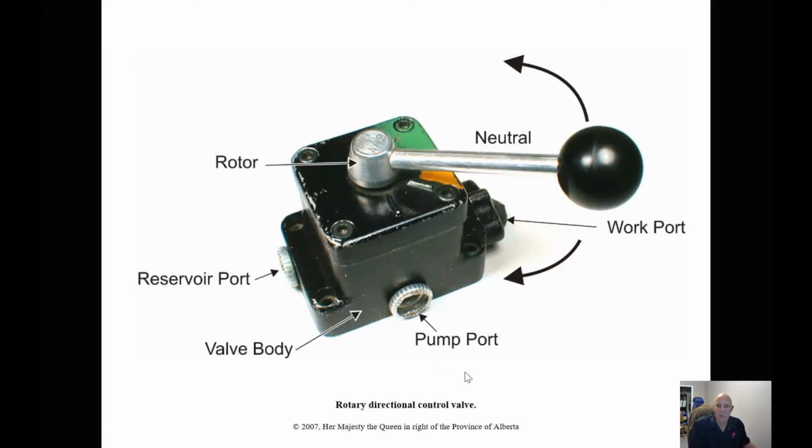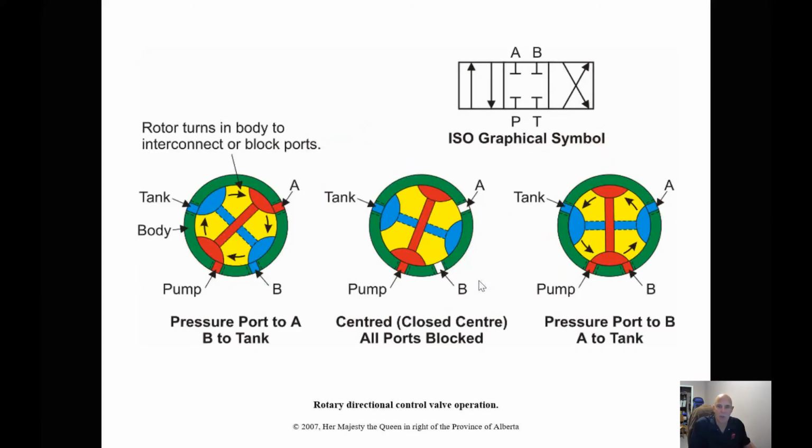When we're dealing with spool valves, there are also rotary direction control valves. Really what we're doing is taking oil from our inlet and redirecting it to whatever component we want. How we do it doesn't matter, as long as it's set up correctly. When we take a look at a schematic, we wouldn't know that it's a rotary spool valve just by looking at it, because our schematic tells us that this is a closed center system. So pressure builds on this side of the system. On a closed center system, we're going to use an axial piston pump, and return to tank is closed off. As we start to move the valve, it's going to allow oil to go out to one side or the other.